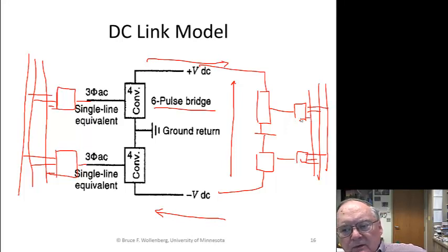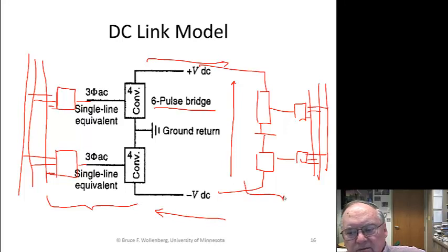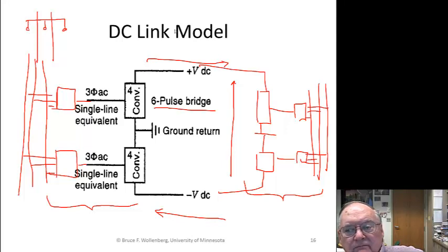And this is done for several reasons. Why go to all this trouble? This is very expensive. But the idea is that with a direct current transmission, we only have 2 wires. So instead of this for a transmission line where I have to have 3 insulators, this is a simple single circuit 3-phase line. I can build it like this. Well, it's only got 2 insulators and 2 conductors, so it's 2/3 as expensive for the insulators and conductors.